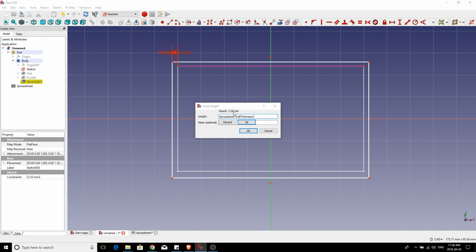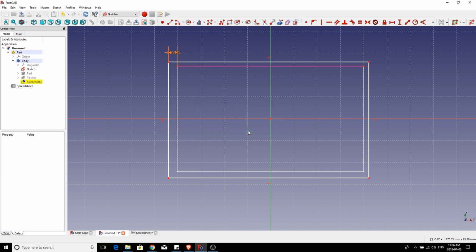That's because if you remember, our wall thickness is set to 4 millimeters, which means that we're going to be plunking this line directly halfway through our wall, all the way around the outer edge of our box. But let's not forget, we also need to include that offset. There we go. So that's that little bit of space between our card and the inner wall. That looks pretty good to me. I'm going to hit OK.